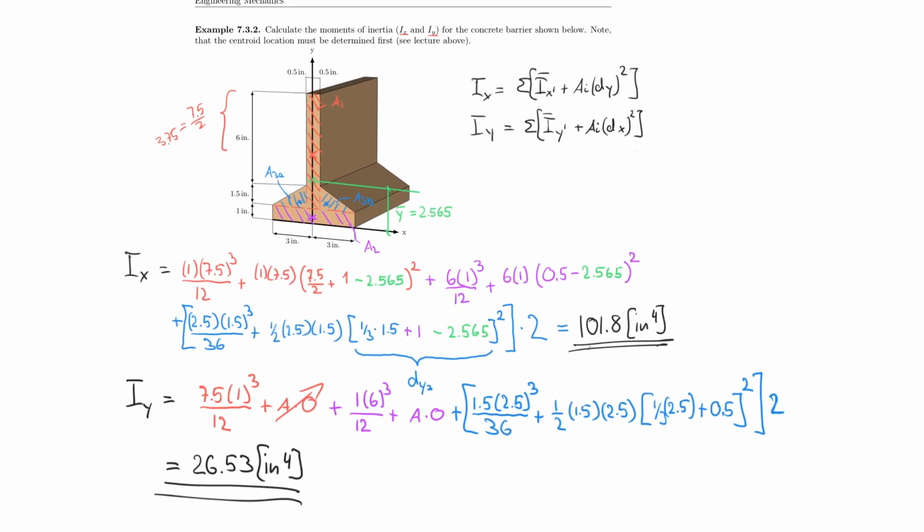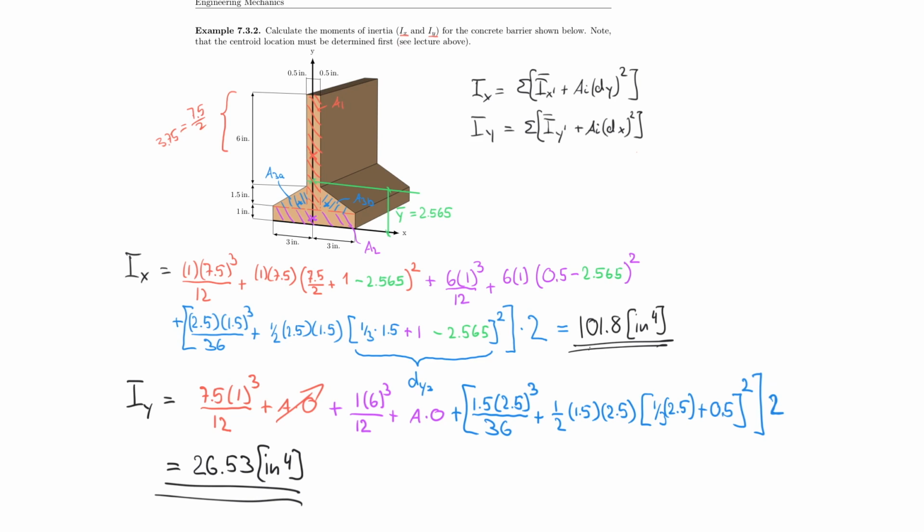So now I encourage you to calculate problems like these. I think we have deciphered it, and we took the next step to include actually our triangles here. And we also have a better understanding now of the centroidal distance, because we have them removed here in the y direction and then here in the x direction. And that should give you an insight on how to calculate Ix and Iy in any scenario,